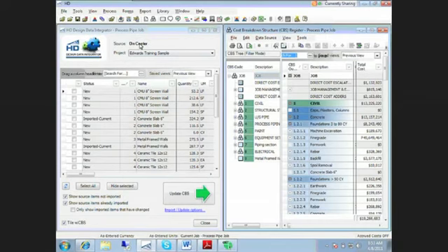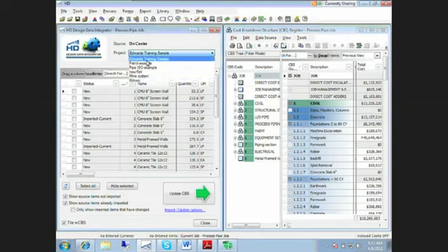Okay, now you can choose the project that you want up here. So this drop down gives you the list of the projects. So it reads that right from OnCenter, so it knows what projects are in there. So we want the Edwards training. If we want to make sure we got the most recent quantities showing in here, we can just hit that refresh item list button.